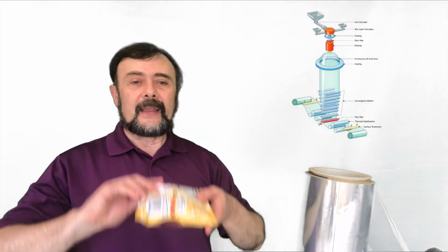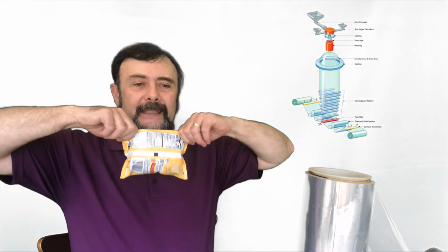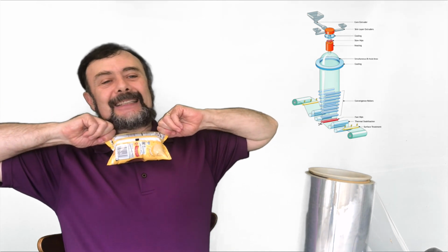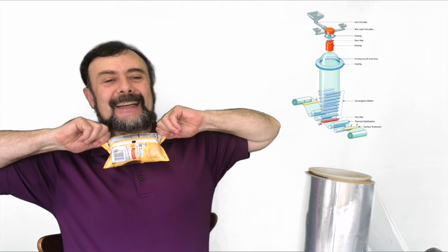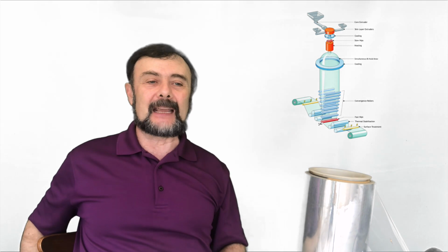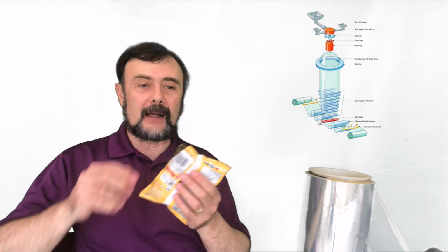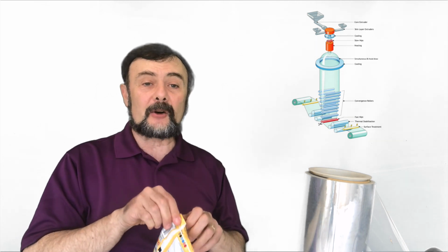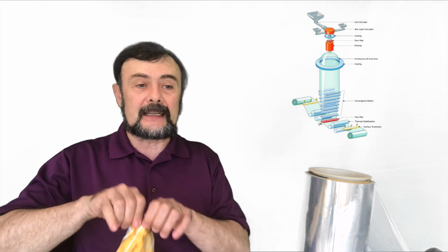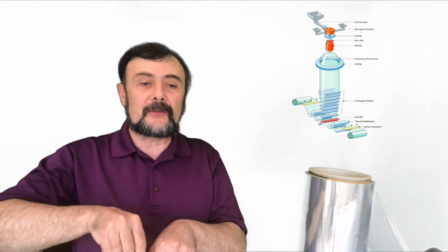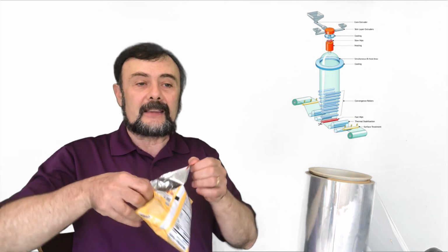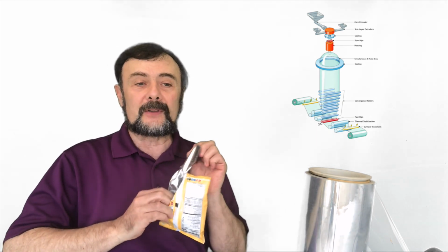That's why, if you're pulling on a potato chip bag on the ends to open it, you'll probably fail. You're pulling in the same plane as the film strength. But once the film is cut or torn, it tears very easily because you're pulling across the film's weak axis, the thickness of the film, and it opens very easily.